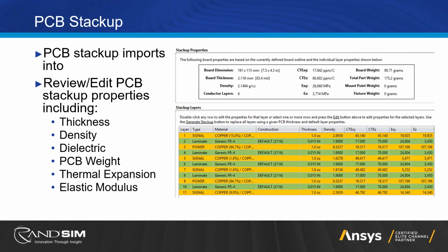But also it's taking all of this into effect. So it's not just taking a smoothing, mean or average of the total weight or density of your board and running the simulation on that. It's actually looking through layer to layer to calculate through how that flexion may occur.